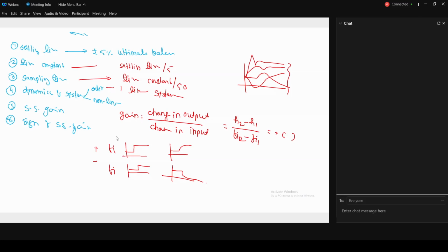Correct? Now, with this information, I can implement step changes on all other variables, which are the potential manipulated variables of the system, and compare all of this, with knowledge of which variable is good for maneuverability. Let's assume you come up with concentration as the manipulated variable, but you cannot change the concentration of inputs so often.